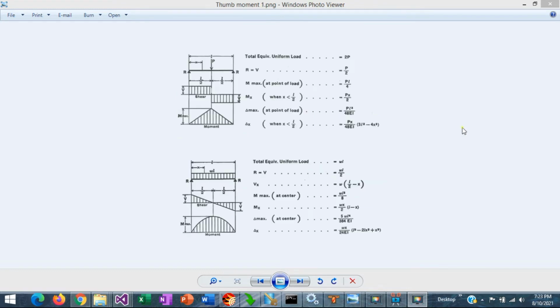Depending on the applied loads, both the shear forces and bending moments vary along the beam to comply with the static equilibrium of forces. Formulas have been developed to calculate the shear forces, bending moments, and deflections for single span beams with different loading and support conditions. These equations are useful to quickly calculate the maximum internal forces in the beam.